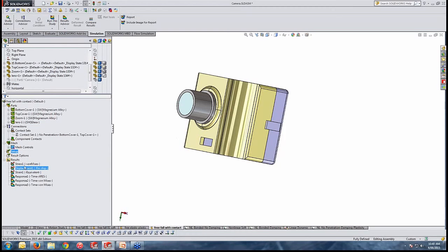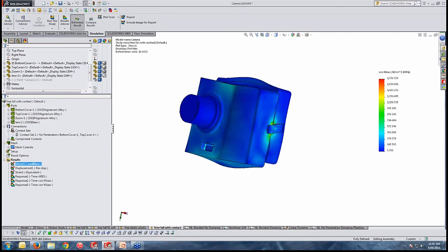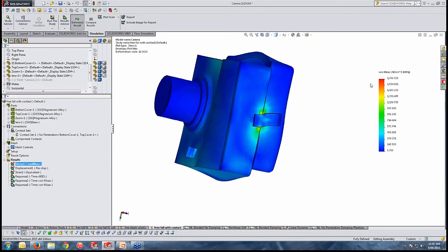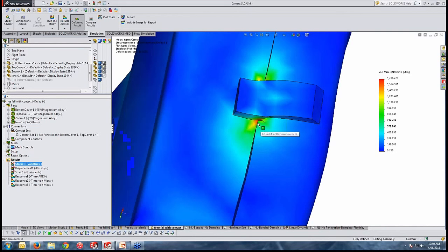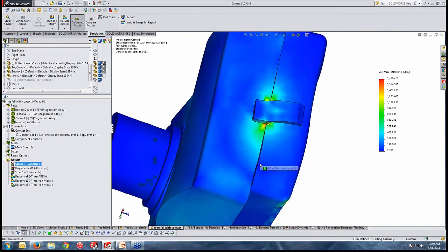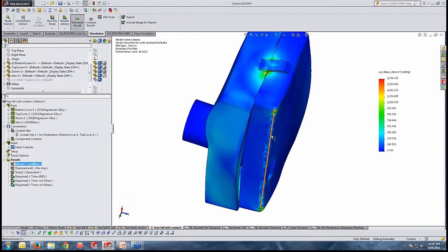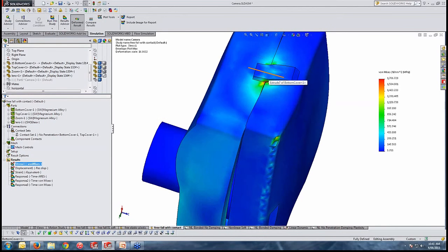Now look at the stress result, and you can see a very, let's say, important magnification. Very high stress, since these two components can act separately and they have a contact, we have a stress concentration, a very high stress concentration at their contact area. Also, as we expect, we have stress singularities on impact, that is expected, but since these two components can be separated, we see the stress. Well, that is considerable information to consider for designing this, let's say, snap-through assembly feature.